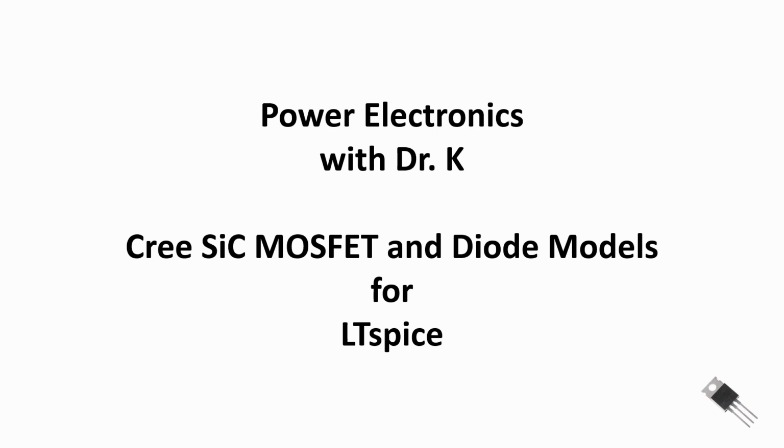And in this video, I'm going to show you how to model silicon carbide MOSFETs and silicon carbide Schottky diodes in LTspice. We're going to utilize the Cree library for this example.